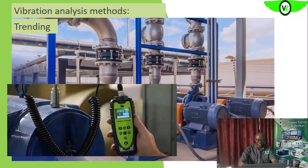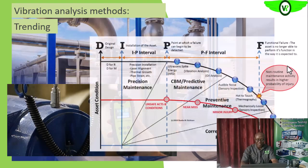As you can see on the screen, this is handheld vibration information. The probe is on the vertical axis, which means you trend the vertical, the horizontal, and the axial direction, on both the inboard and outboard ends of each piece of equipment, so that when the trend is changing, it becomes very visible. That's with the handheld. So if you have a low budget for this technology, you can use this.